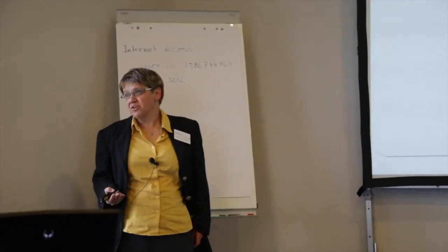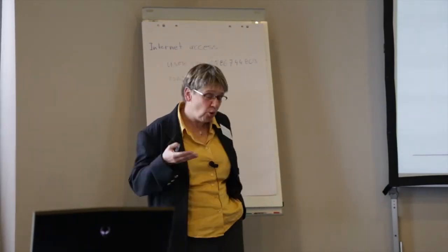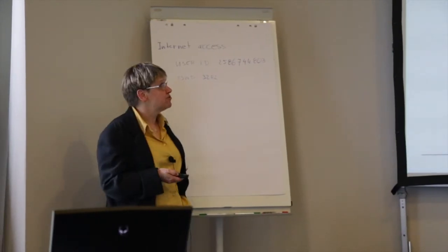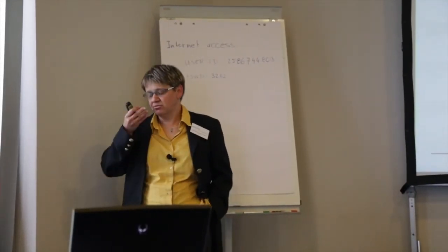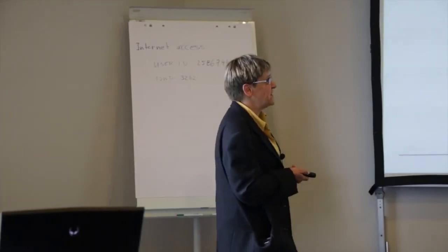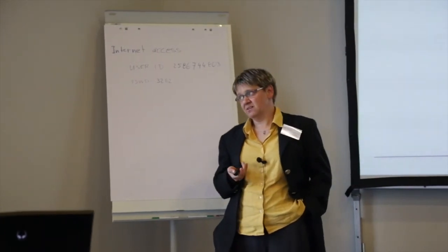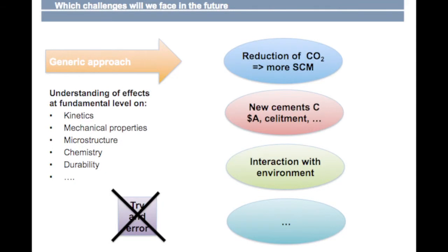Now, if we think a bit further to the future, I spoke a lot about fly ash and slags and silica fume, and this is quite well known by now. But in the future, we will have to continue to work towards the reduction of CO2 emissions. We also will face the development of very new cementitious materials, like they already do nowadays. You can read a lot about calcium sulfoaluminate cement, you can read about belite cement, but I'm very convinced in the future there will be much more coming with different chemicals, and there we cannot just use our previous experiences to understand what's going on.